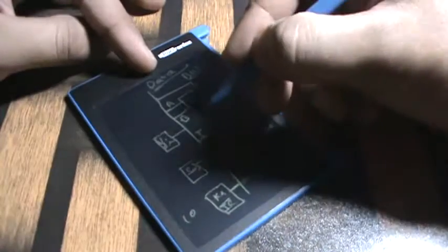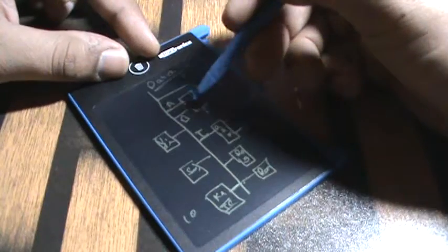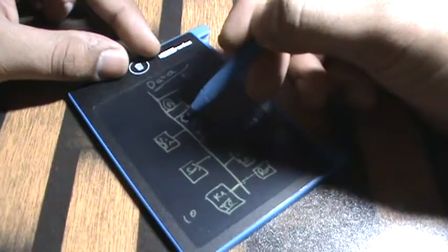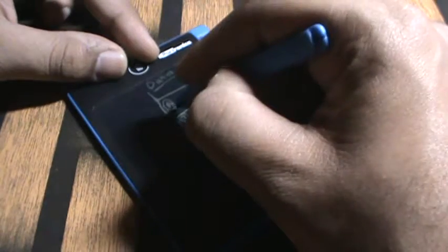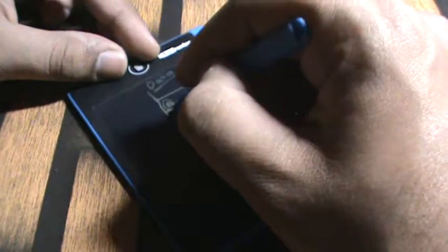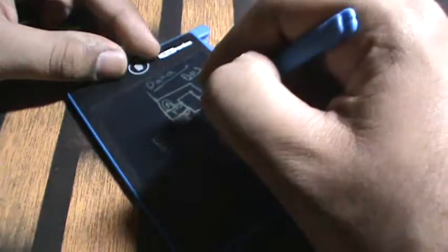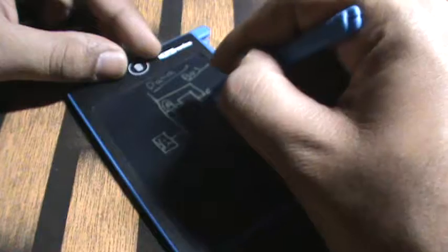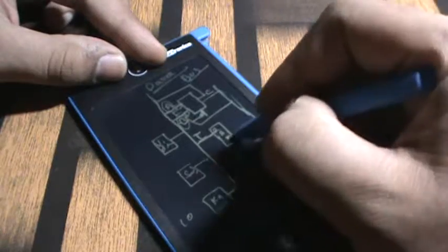Then the processor is going to get a clock signal from the clock. Then our processor is going to decide whether this value of 10 should be saved in A or in B. How is it going to do that? There's an AND circuit attached to each and every input of A and B, and the output of A and B is going to the processor's address line, not to the clock signal. I'm sorry about that. It is going to the address line, which basically defines which one. Okay, let me draw this address bus as well so that it doesn't bother us anymore.